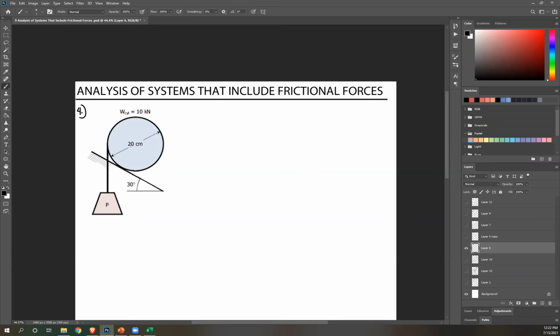So meaning, whenever we have a non-concurrent force system, we usually use the concept of moment. So now how do you use that? So to use that, I need to choose a moment center. Okay. And for a system like this, there's two choices. One is at the center of your cylinder, and the other is at the point of contact. So let's try at the point of contact, right? So let's just specify what's happening, right? So this has weight. Weight is always at the center. So there's a downward force here. That is 10 kilonewton.